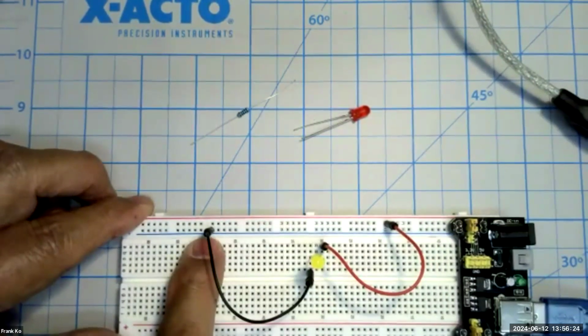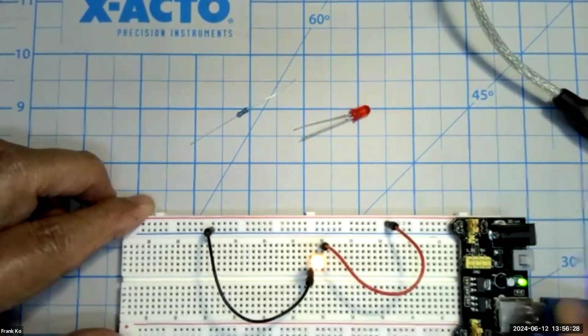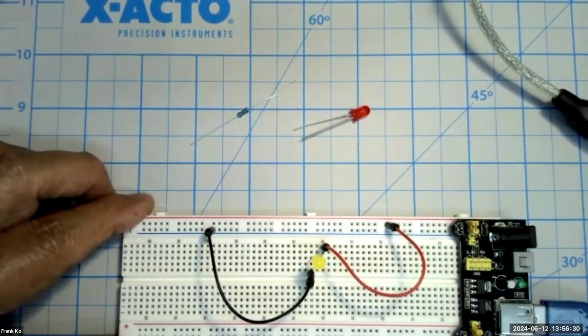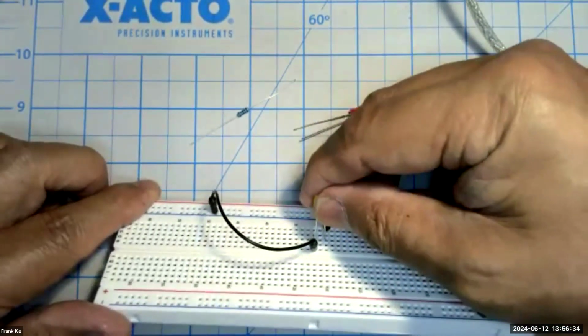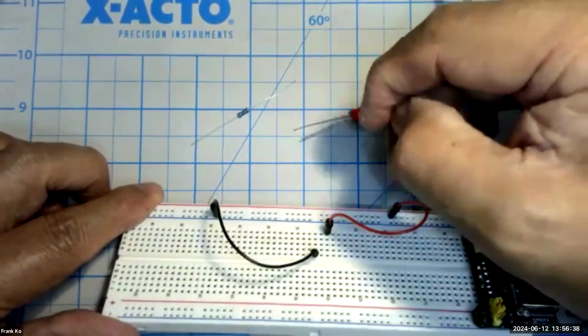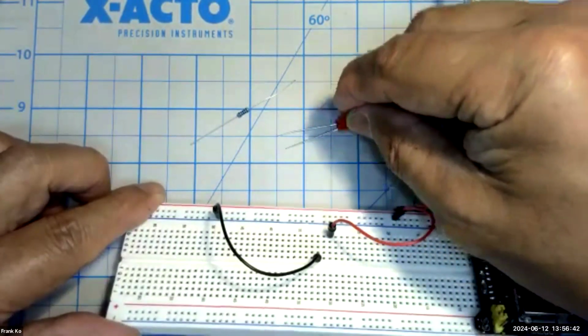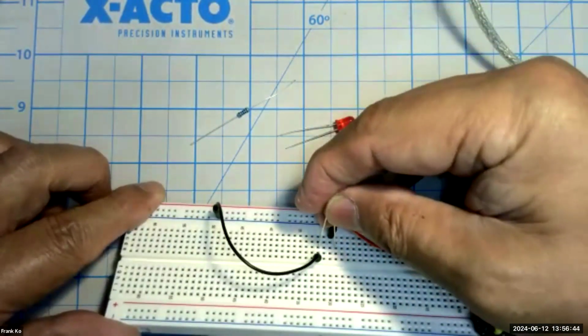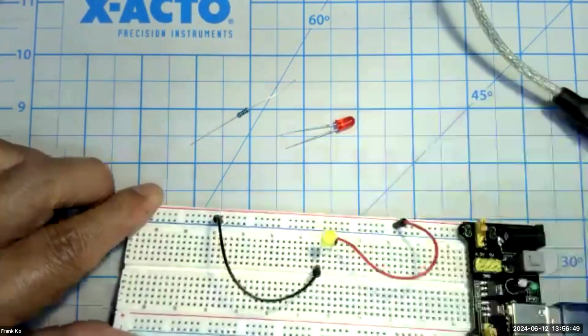So if, for example, I go to hook this up and I light this up and the LED does not light up, well, it could be a variety of reasons. The most common reason is that the LED is backwards. So if I take this and flip it around, and you can do this in your sweet time as well, very interesting, so that the long lead is facing the wrong way. Push this down.